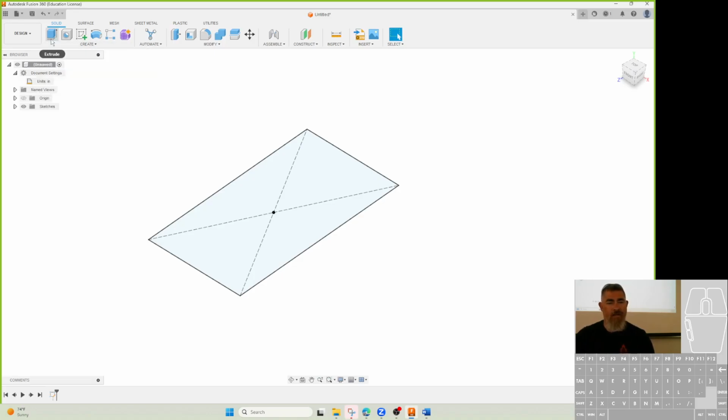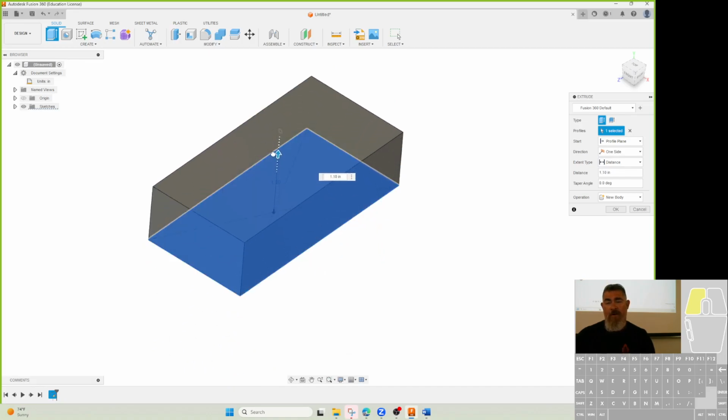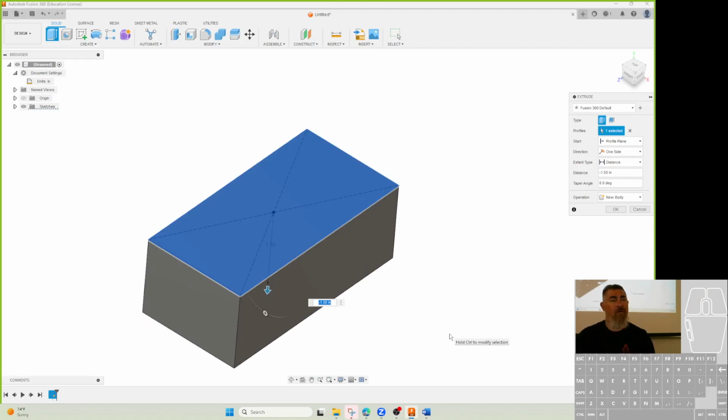Just like Extrude shows, it takes a profile, the gray thing, and makes it go up. If I pick on here, I can drag it up, drag it down. Notice if I go up, it's a positive number. Go down, it's a negative number. That's the way any plane has a direction: a positive direction and a negative direction. On a regular plane, coming towards you is the positive number, and going the opposite way is the negative. If you're sketching on a part, positive is away from the part, negative is into the part. I'll show you that in a minute.